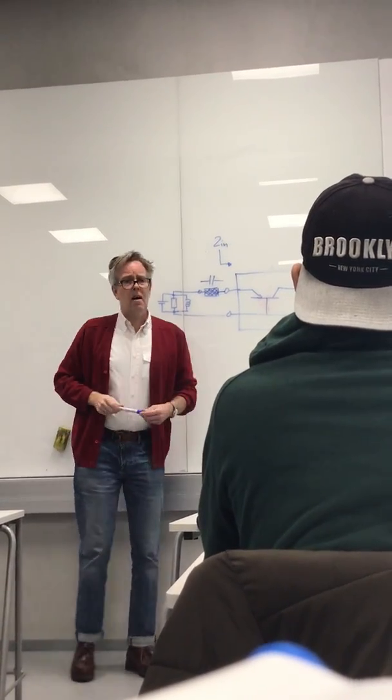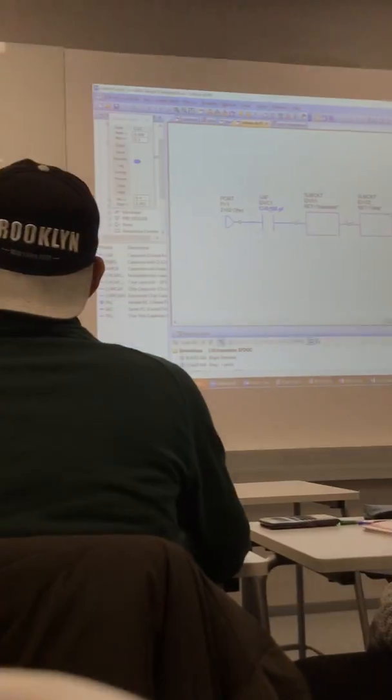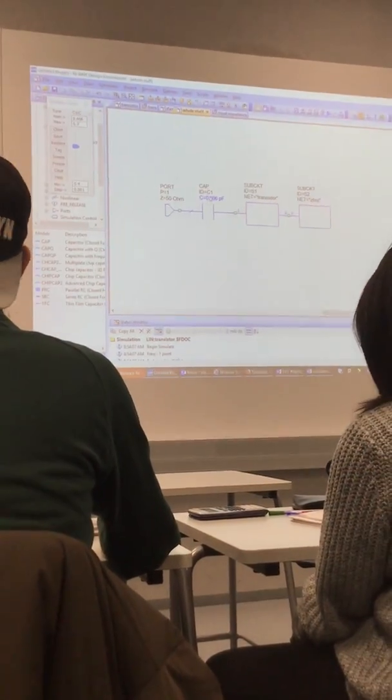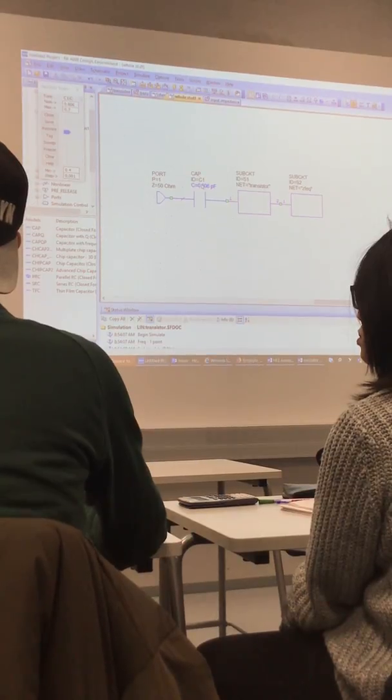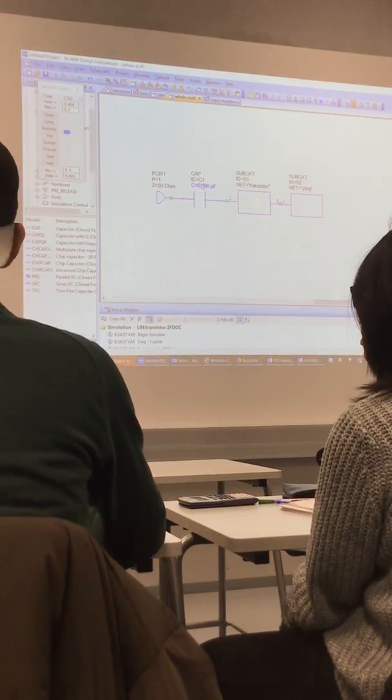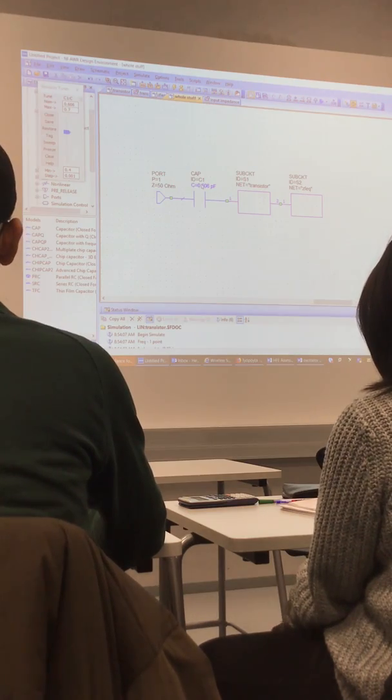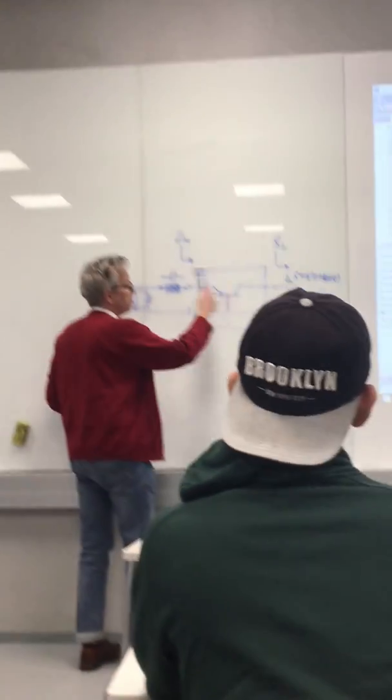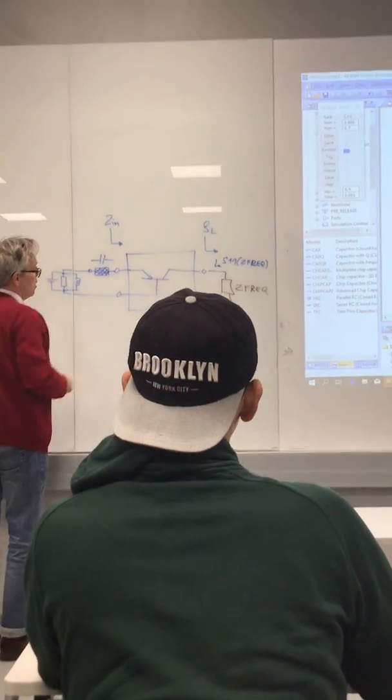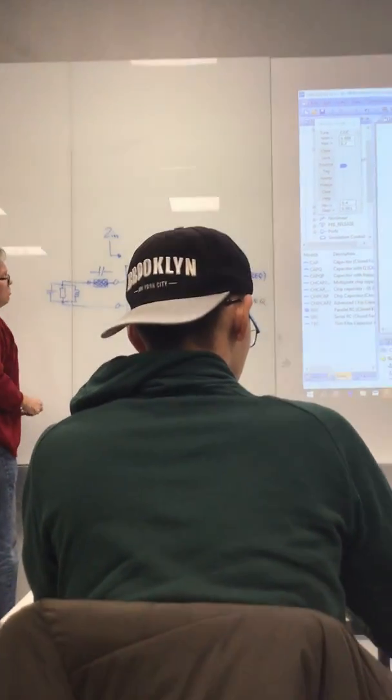Then I still ask, after this, I ask you to complete a few steps on paper. This is basically done now with the microwave office. We've selected a proper reflection coefficient to the output to create a negative input resistance.